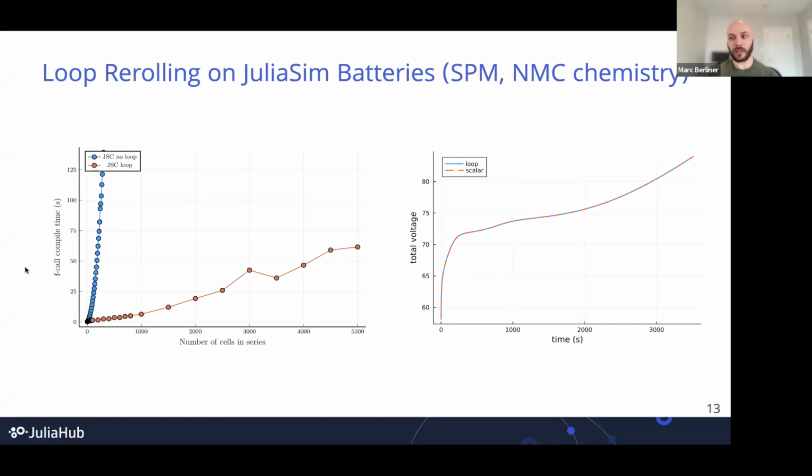At this point, we don't change too much of the cell geometry, like comparing a cylindrical cell to a pouch cell. If there are other thermal aspects, we can model these with things like lumped thermal analyses or including electrical resistors that may include some effects.